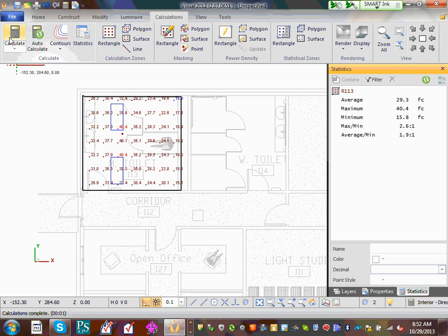It's higher than what we asked for. So I would rather have two fixtures with higher than one fixture, because in bathrooms you really need two fixtures because of the function. You don't want one to turn off, the ballast goes, and then it's dark, right? There's a better way, guys, of doing it. Go dig and find the type of fixture that we're using is hard to get. We're using T8. Let me show you. Can I have a thumbs up, Chad? Let me repeat the function before my friend comes here in a second.